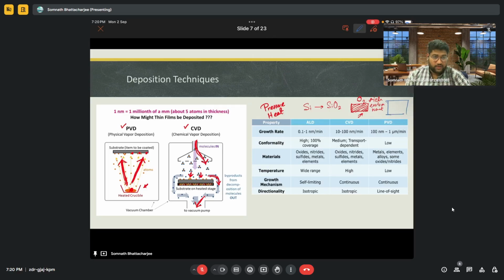It will increase in volume, and it will be divided into 45% and 55%. So the silicon will get oxidized. Let's say this part is silicon dioxide, and the darker part is the silicon. So it will get divided into two parts.